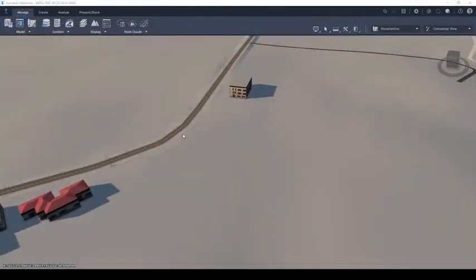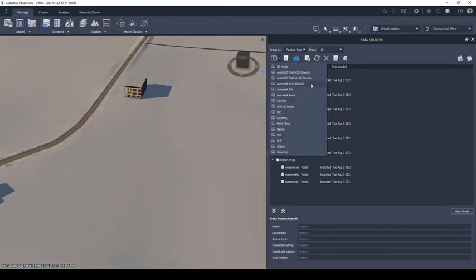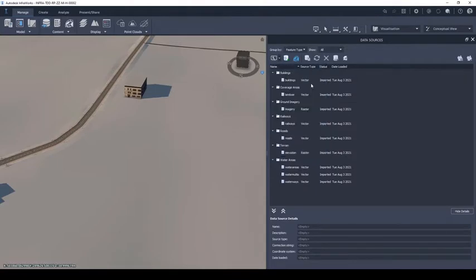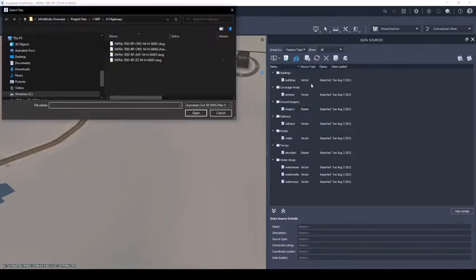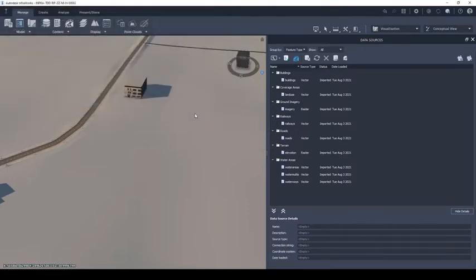Back inside of Infraworks, we have the ability to import Civil 3D surface data into the model once further project work has taken place. This could be surface data taken from an updated survey, giving more accurate elevations on a further refined grid, an exported surface from a linear corridor, such as a road, railway or earth embankment, or it could simply be a proposed tin surface created inside of Civil 3D, using points, feature lines, and so on.